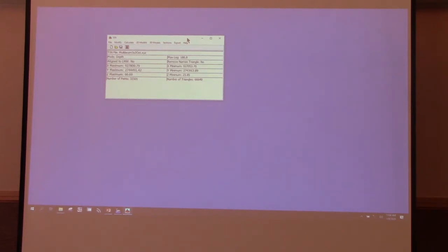So everyone understand about border files? Do we want to talk about border files for a second? A border file we generate is just the polygon, and then the final point is whether you care about what's inside the border file or what's outside the border file. The border file can be used to exclude data from a set of data, either cut a hole in the middle, a lake, a void in your data, or to eliminate spurious data around the edges.